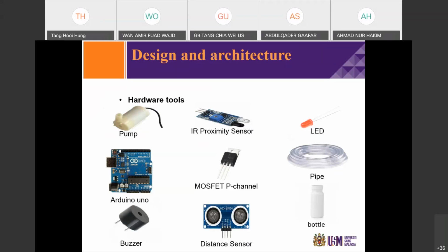So what about the distance sensor, Arduino Uno and buzzer? Those will alarm when the device does not have a sanitizer, which means that the sanitizer is finished. So the distance sensor will measure the distance from the bottom of the bottle. Then it will be on. After that, the buzzer will turn on to alert the security room to come and refill the sanitizer in the device. Next.